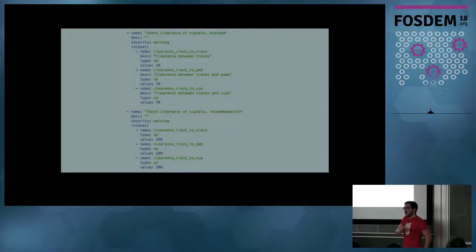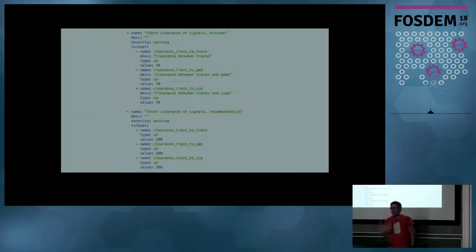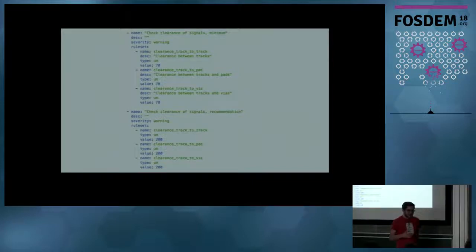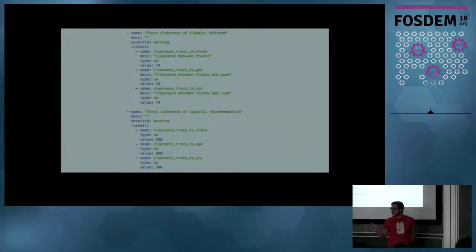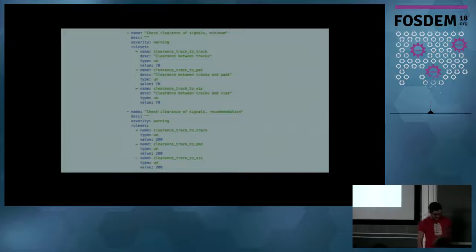But what I really would like to introduce is the severity, because this really bothers me as a PCB manufacturer, that people always go to the limits. If you want to place 2 tracks between 2 SMD pads, it's fine if you go to the limit, but please don't draw 5 centimeter tracks with 0.1 millimeters. No, please not.